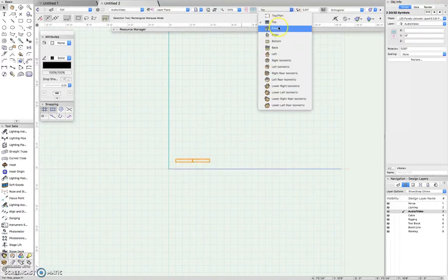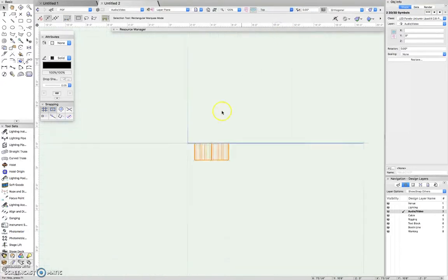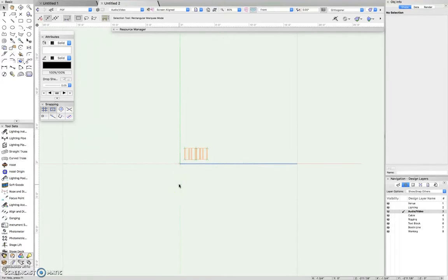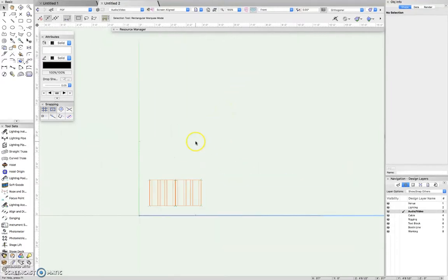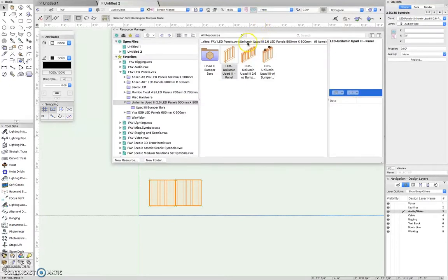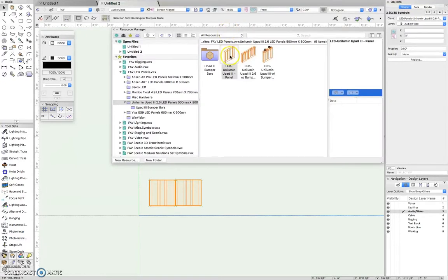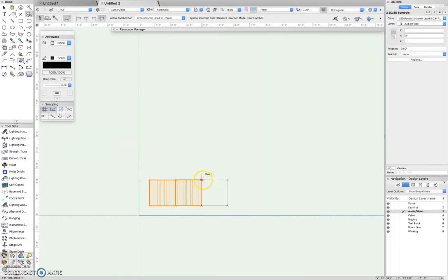If we go to the front view, I'm going to go ahead and just build this entire wall from the front because that is the most straightforward way to do it. What I usually do is, once I've got a tile in there, so I don't have to drag every individual one and just drag a new one. Well, okay, you can do a couple of ways. So I'm going to do this row where you want to click. You can see I've got the insertion point in the top left corner, and it kind of snaps to that corner of that tile.